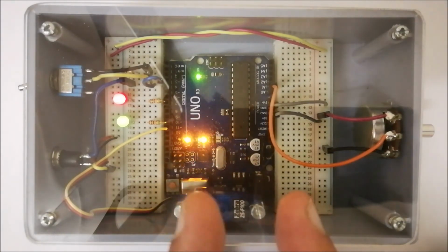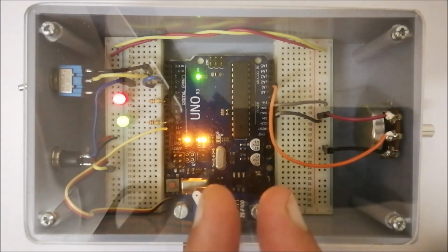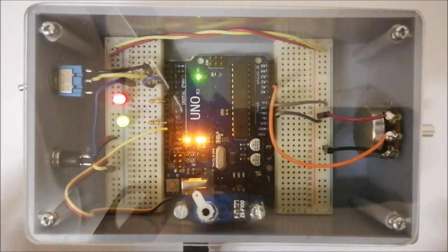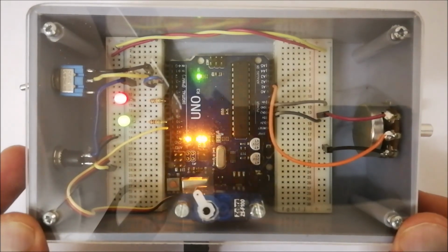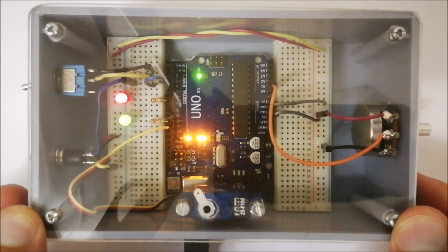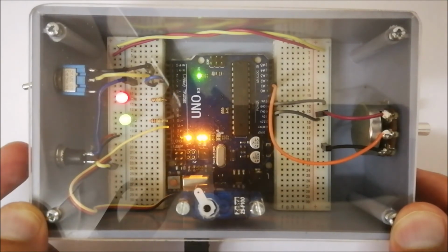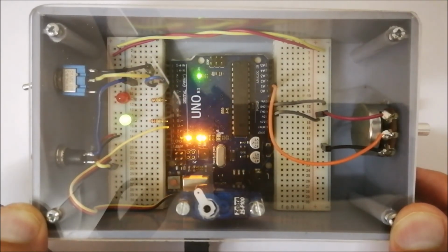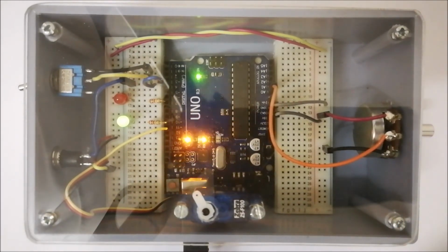So you've got to be very quick with that push, to make sure that there is a very short time period that it's activated and that there's no clapping happening between those two contact points inside the push button. So if I push it again, there we see it still stays on. Okay, there we go. Push it again. Now it switches off. So you'll see that in switching from one state to the other, even though sometimes we have to push it quite often to get it to recognize the activation, it is a more steady output that we get, and we don't get that flashing happening with the LED.